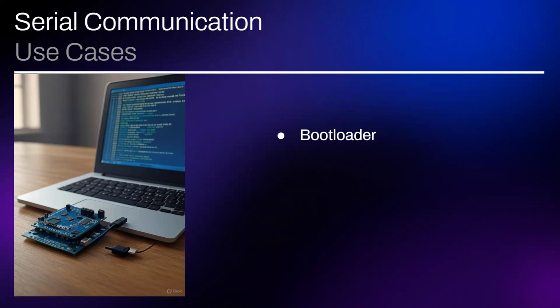So the concept of a bootloader came up, where you take it out once and put it in your programmer, and you put a little program in there. And that program talks over a serial port or some sort of communication device, and you can write a program to it, and it will stick the program in memory and then start executing that program for you. And maybe there's a little button on there that lets you break back into the bootloader when you want to load a different program on, so you don't have to remove it all the time. So that's what a bootloader is in an embedded space. So it's a much easier model.